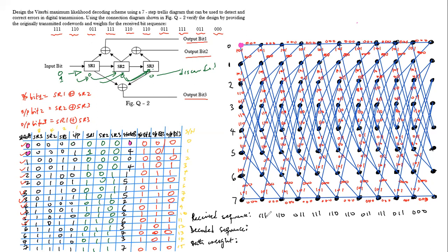What the algorithm does is to benchmark what was received with the code words given that particular path. Now we have the input coming in this way. Once we receive the input, it's 111, so we check for the pathway. Should we go this way, upward? That's with 000. Now the weight using modulo-2 addition is 111, so we have three ones here. The pathway weight is three.